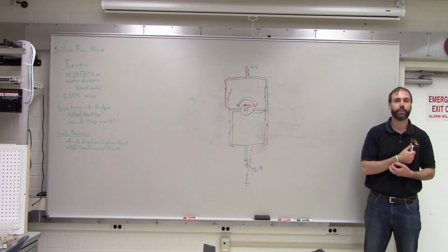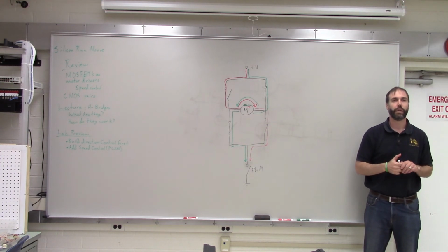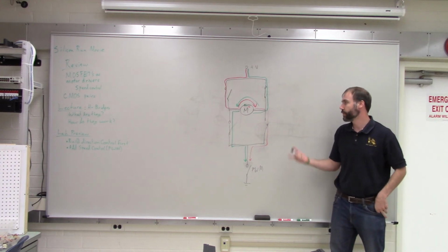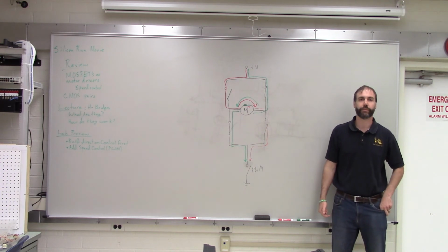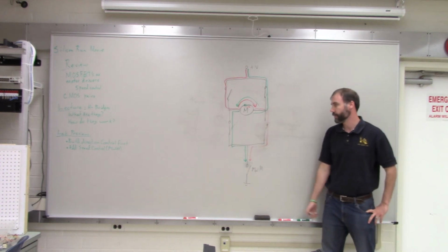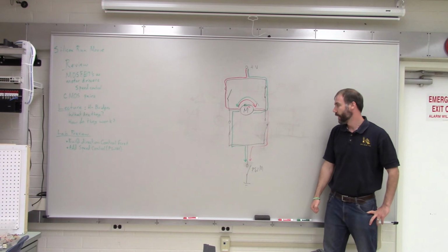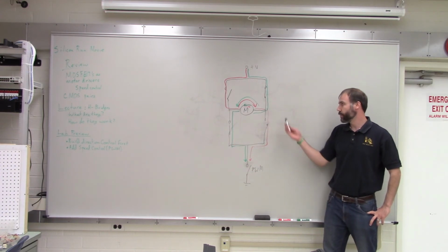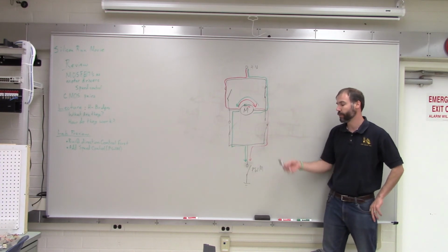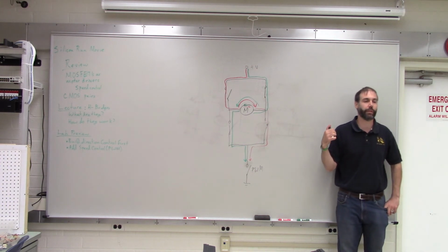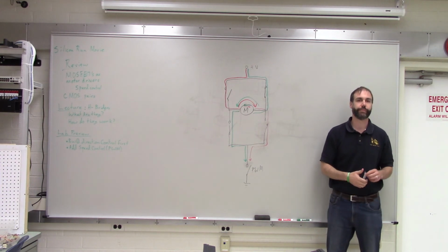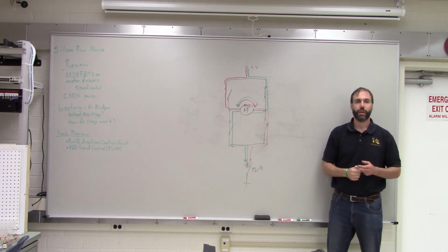Yeah? Is this switch transistor the same kind of transistor or different? You can use any type of transistor that you want. We're going to use the same kind that we used last time. It's still a MOSFET transistor though. Yeah, we're using MOSFETs in this case, but you could do it with BJTs also. If you were using a really big motor, you could use a type of transistor called an IGBT, and we'll talk about those in a later lecture. But the principle is the same. Other questions?